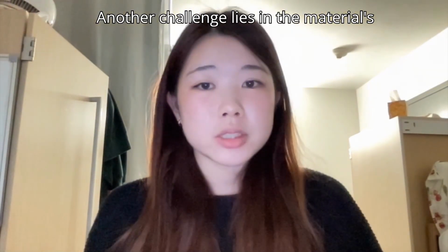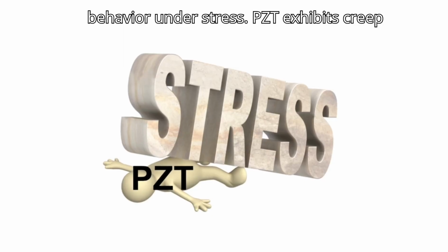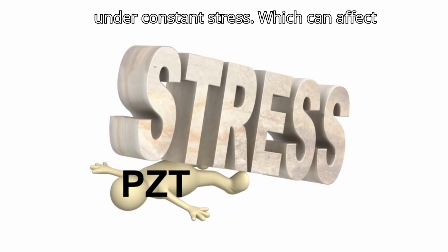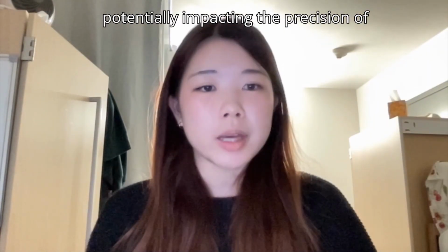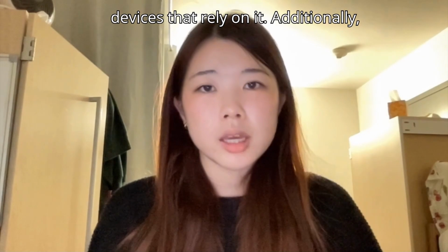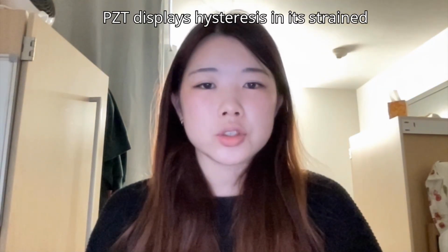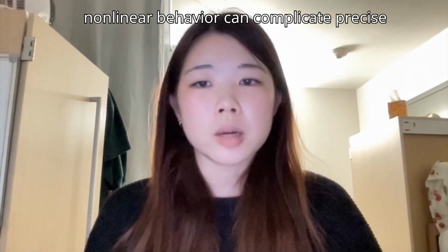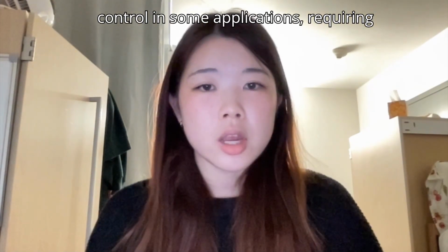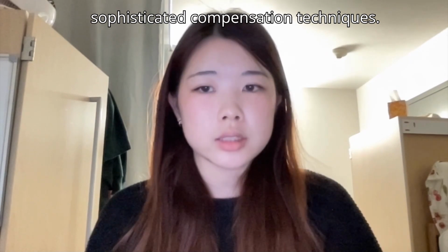Another challenge lies in the material's behavior under stress. PZT exhibits creep under constant stress, which can affect its long-term stability. This means that over time, the material may slowly deform, potentially impacting the precision of devices that rely on it. Additionally, PZT displays hysteresis in its strain-electric field relationship. This nonlinear behavior can complicate precise control in some applications, requiring sophisticated compensation techniques.